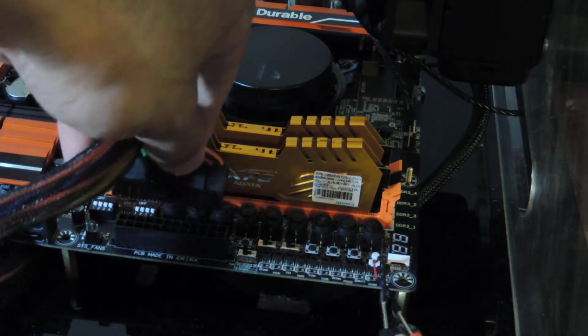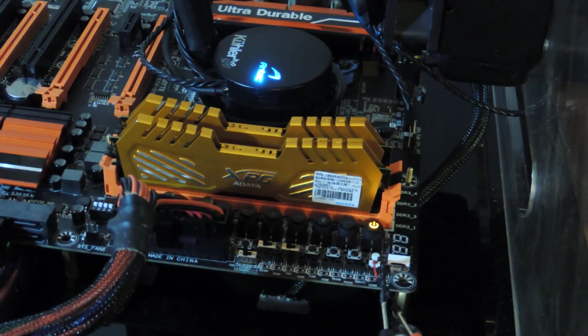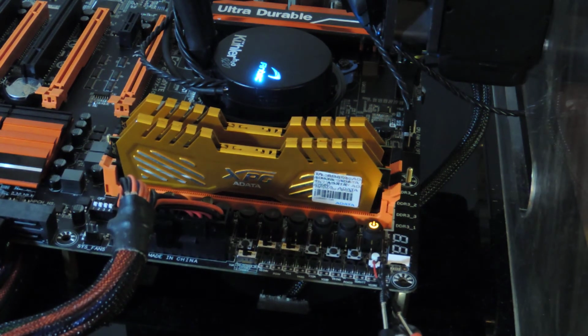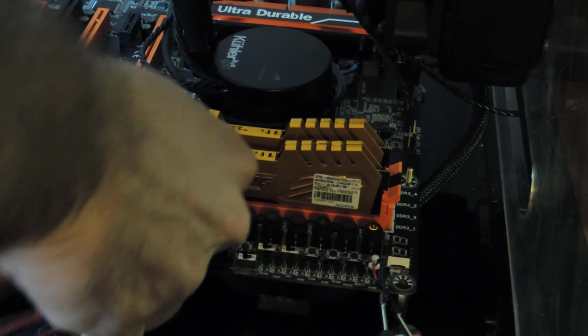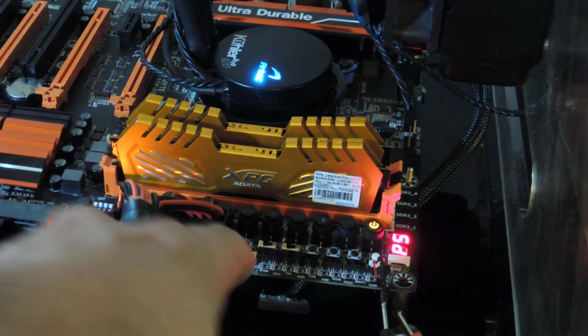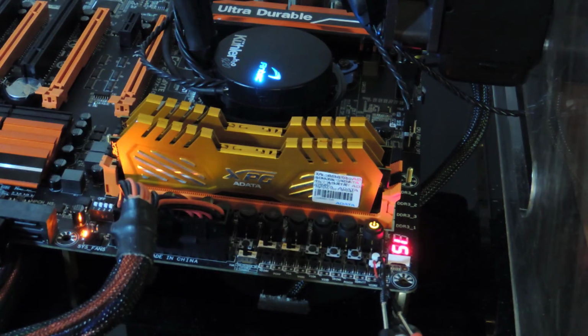So if I put this back in, okay, and now I press, everything starts up fine. Alright, cool. I press CBAT again, power drain, still can't start up. Remove 24 pin, put it back in, I can go up and down. But clear CMOS is different. So clear CMOS, if I hit it, it's just going to clear CMOS and reboot.